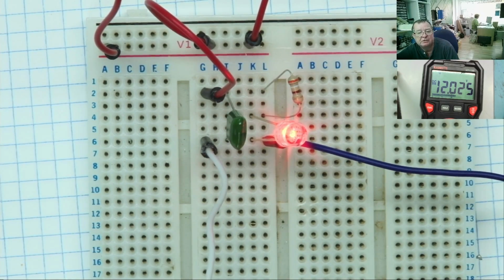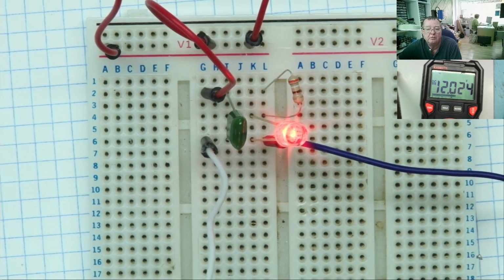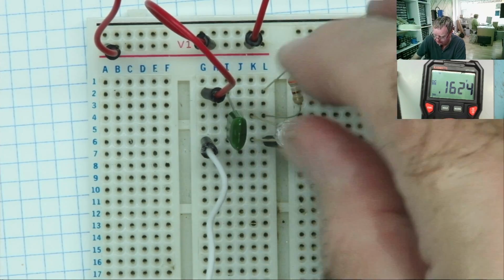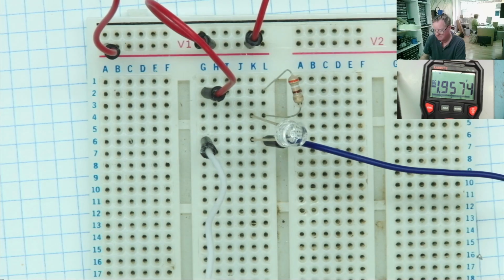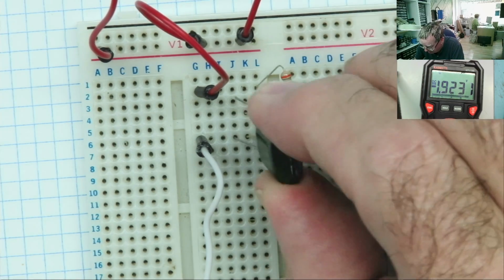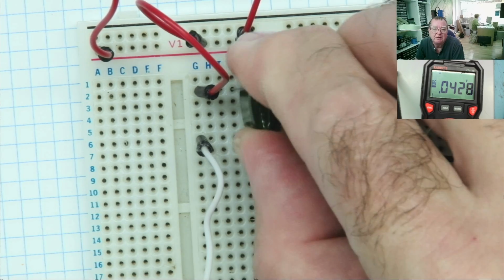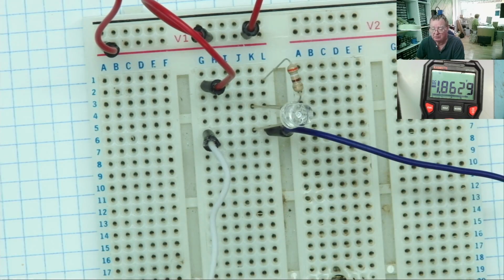Well, the LED lights up, and the LED goes back out, just like it did before. Okay, on, off, on, off. So the capacitor in fact doesn't really seem to do anything. Why is that? Well, the reason for that is the capacitor is too low a value to keep this LED lit up for anything other than maybe microseconds. So we'll fit a larger capacitor.